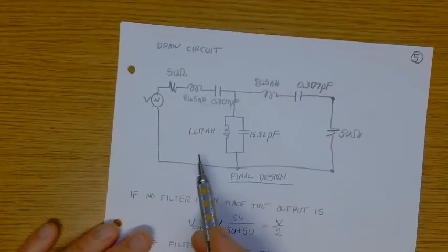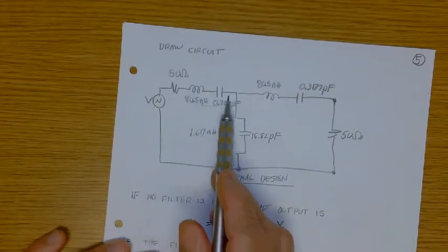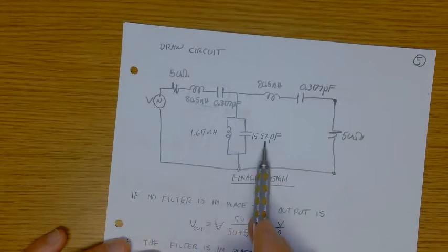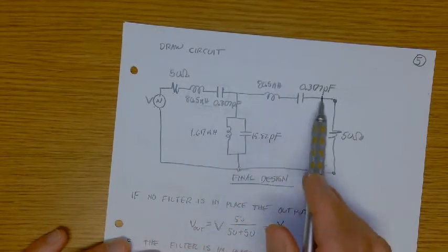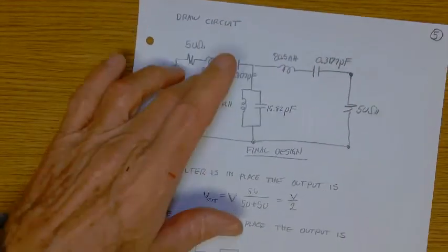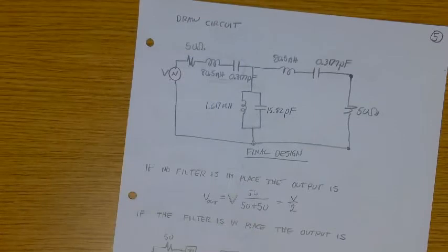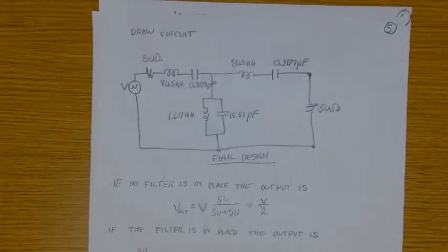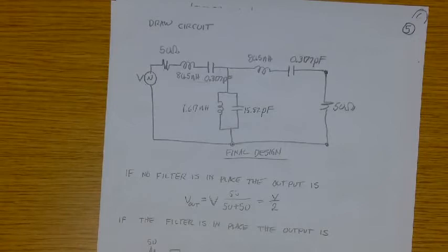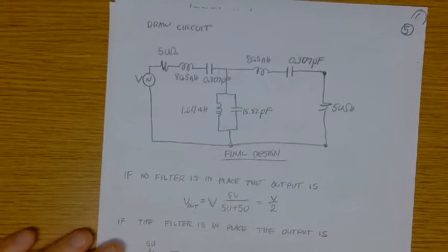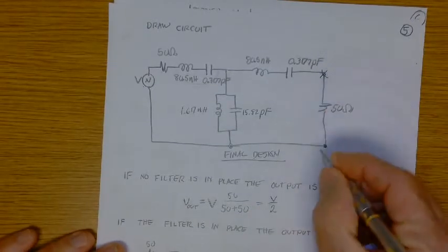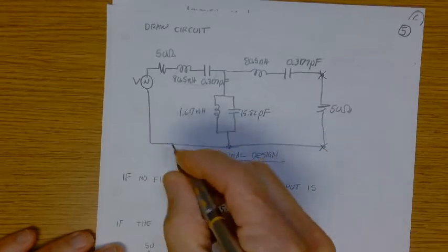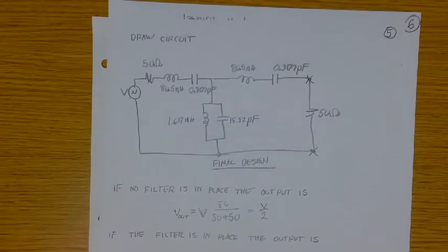So now we've got the design. Let's check it. We want to use our numerical tools, because doing it by hand, my gosh, that would be a pain. But use whatever numerical tools might be handy for you. PSpice is another good way of doing it: create the circuit pretty quickly and get the frequency response from it.